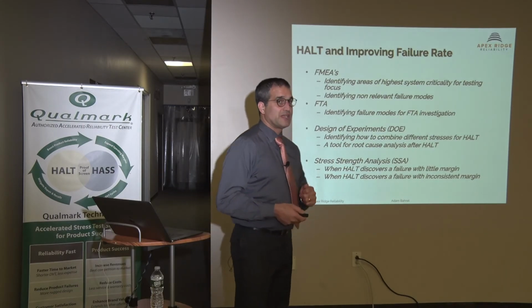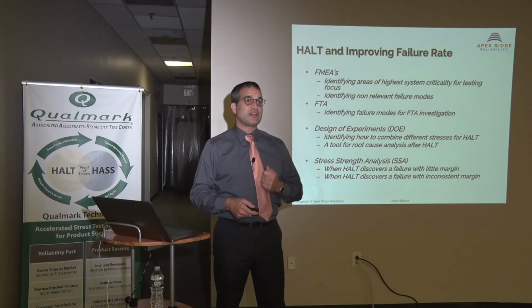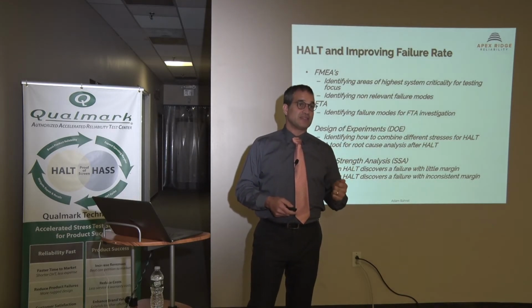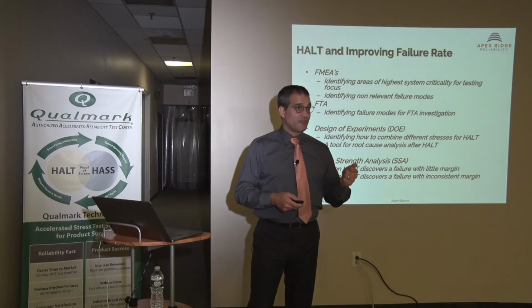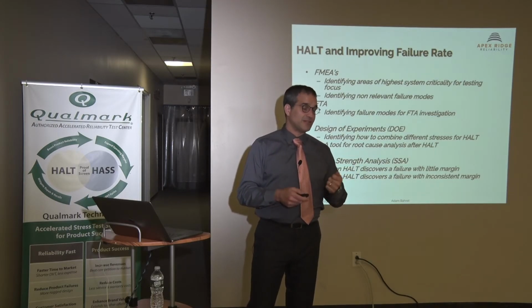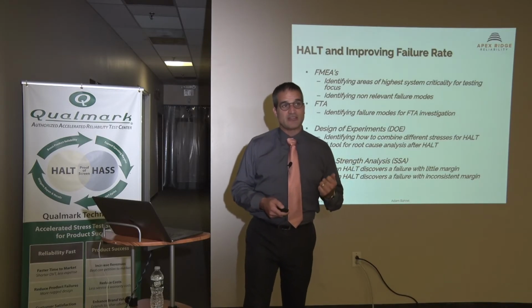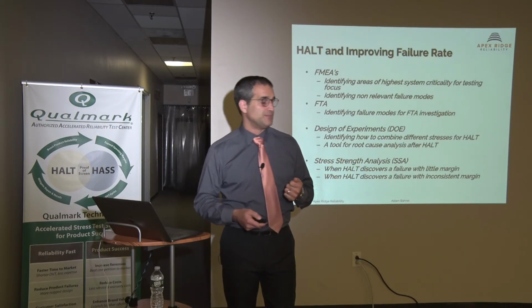You have fault tree analysis, and this is having a specific failure and trying to understand the root cause. So again, you can see very easily how this links to HALT testing. You found a fault and you're trying to understand it. Well, that's one of the purposes of HALT, to find faults for you to analyze. So you can see how it very clearly links to this tool.